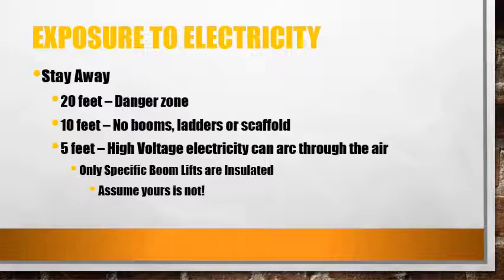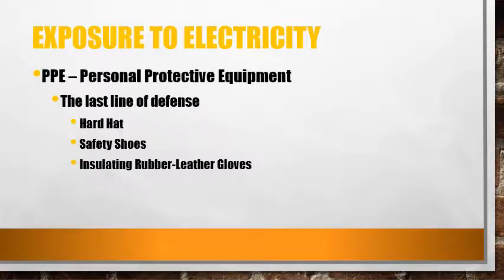you even touching it. Never assume that your boom lift is insulated. Only very specific boom lifts are built to be insulated, so assume yours is not. Do not go within 10 feet of power lines.